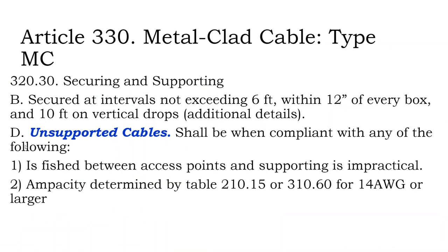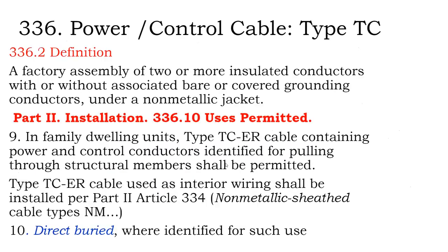All right, so now we have some more rules for metal clad cable. Secured at intervals every 6 feet, 10 feet for vertical drops within 12 inches of a box. I guess you don't need to attach it to every single rafter as you're going across the rooftop.